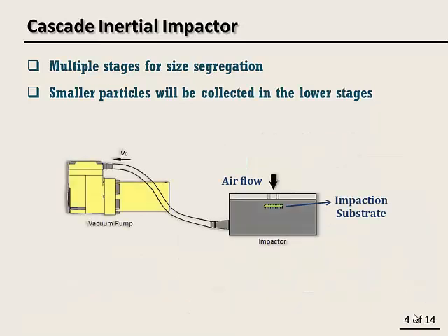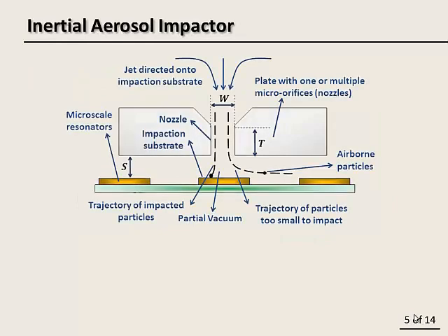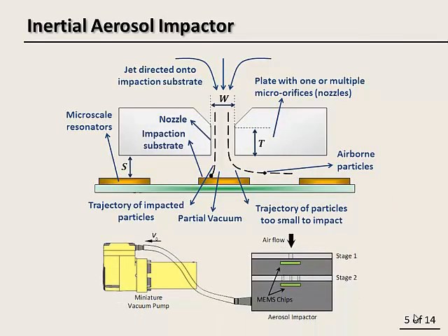We recently proposed a very small, custom-made, single-stage impactor, and we embedded thermally actuated resonators for real-time mass concentration monitoring of particles larger than 200 nanometers. Here, we are presenting a two-stage aerosol impactor not only for mass concentration monitoring, but also to size-distribute air samples from different environments.